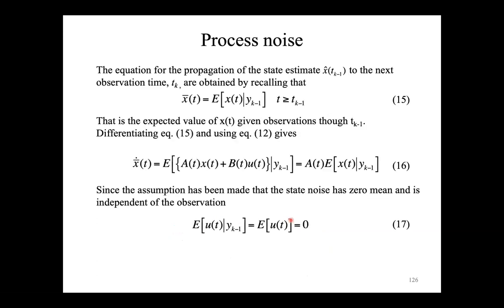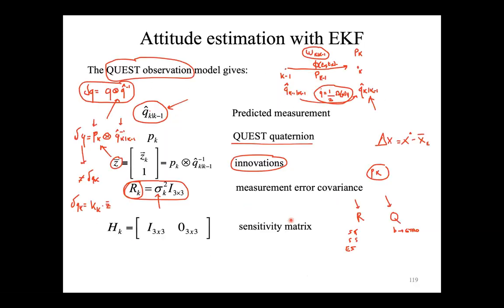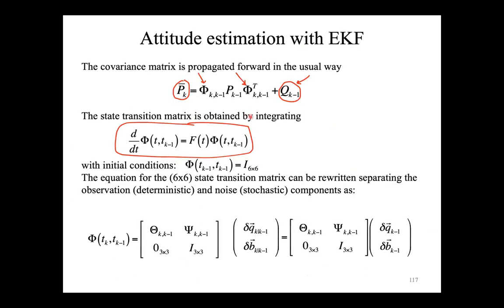So what I was suggesting is that, in order to approach this problem in a simpler way, you can assume that it is indeed the error associated to the gyroscope. So you have an idea of what is the contribution of the gyroscope to the error of the quaternion. And in this particular definition, it is my reference to the tuning of the extended Kalman filter.